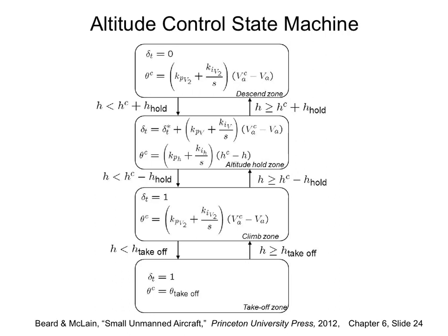So yeah, we are done with all the loops. Let's see how the longitudinal autopilot looks. We start here. You're always checking your height, and when you check your height, you can determine which of these categories your aircraft is in, and based on that you can choose which control to call. There is always a loop continuously checking h so that you can switch between different cases. So this is case 1, case 2, case 3, case 4.